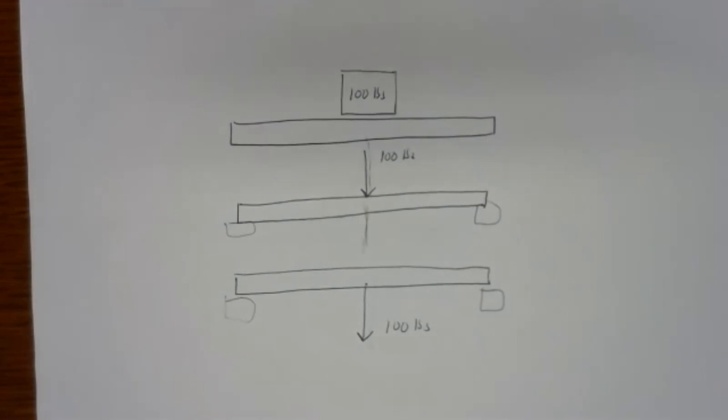So that gives us a tool to help us simplify our drawings. We can move our forces around along their lines of action in the same direction. As long as we don't change the direction of the force, as long as we don't change how much force there is, the physics won't change. So that lets us simplify things quite a bit. So that's a little bit of terminology.